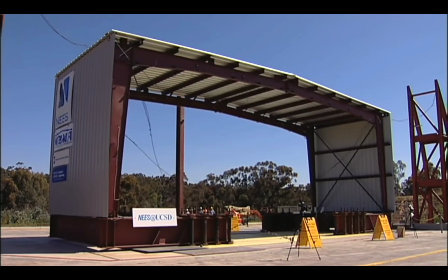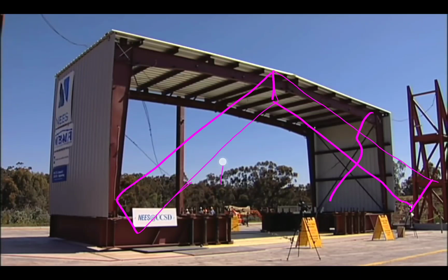Now you can retrofit concrete buildings with what is referred to as a fuse system that can take some cross bracing. It can take a licking, and will bend, will deform, and that will take a lot of the stresses during an earthquake. Of course, you've got the water tanks that people put on top of a building.